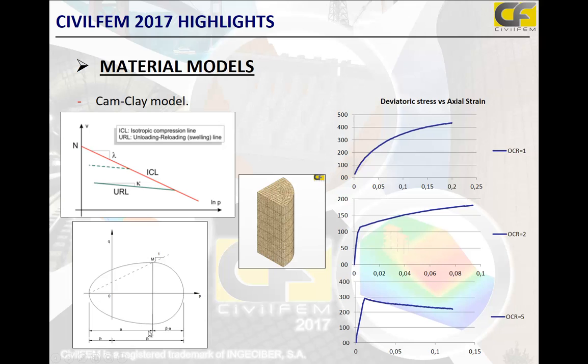This ellipse is defined by E, that is the ratio of it, and also there are some coefficients, beta and pt, that displace this curve towards the left to add tension stress on the model, and also this other beta value just to reduce the curve in this zone. So we can define different shapes for this ellipse and to define the over-consolidation stress.